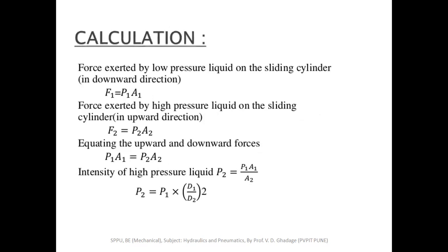Force exerted by low pressure liquid on the sliding cylinder in downward direction, F1 equals P1 A1. Force exerted by high pressure liquid on the sliding cylinder, F2 equals P2 A2.